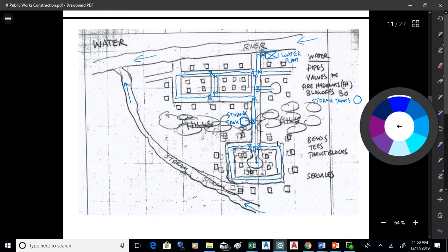All right, now when I put those pipes in there, I need to put valves in. These are typically just on-off valves. So they're gate valves, typically shown with that bow tie sort of symbol. What I like to do when I have intersections is be able to control the intersection, so I can shut off different branches of the system. That way, if I need to work on it or if I have some sort of problem, I don't have to shut the whole system down. I can just shut those valves and then reach that part of the piping system that needs repair or some sort of maintenance. Okay, so the valves are typically on-off valves. They're gate valves. They give me control over the system. Okay. So I've got those valves shown.